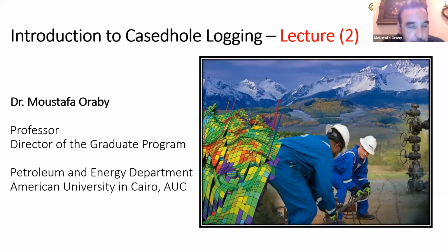Thank you, Mariam, and welcome everybody to the second lecture on the introduction to cased hole logging. In the previous lecture, we covered the inside of the wellbore. So we talked about how to evaluate or identify zones that can produce gas, zones that can produce water, and also how to calculate and define the flow rates, and measure the velocity of the fluids inside the wellbore.